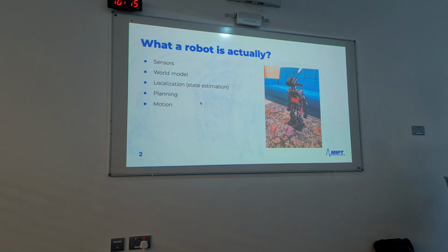This is done with Kalman filters and other stuff like that. So filters that are based on the stochastic nature of the measurements. We assume the sensors to be noisy and to try to estimate our position as good as we can.